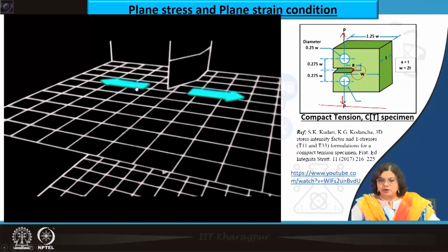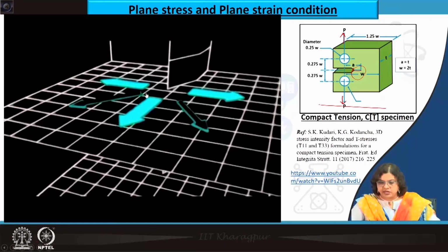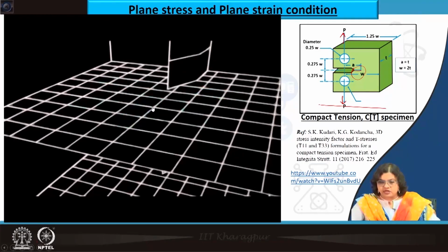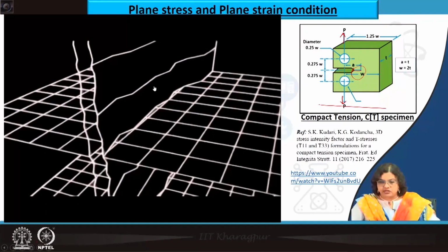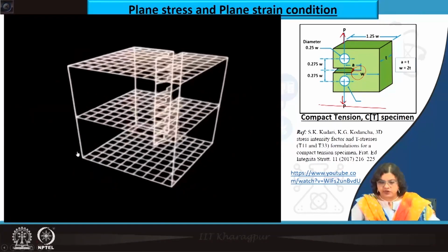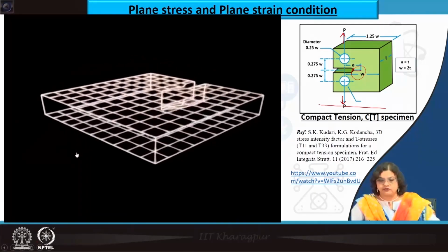So, if we are talking about the fracture surface, these are the stresses that are being applied, tensile stresses, and there are the shear stresses along 45 degrees. But since these tensile stresses are mostly active, fracture is happening along this way, which is leading us to flat fracture.